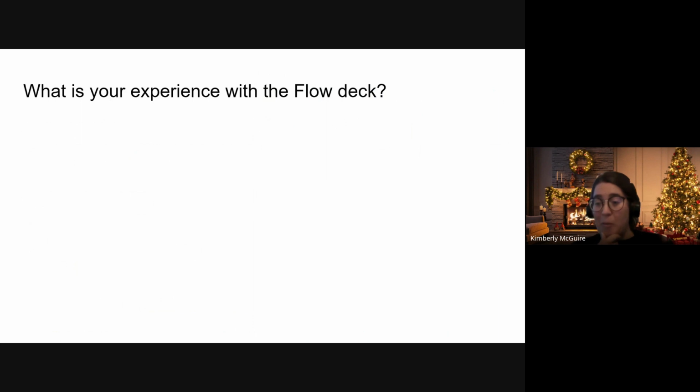So you just have to hope that at one point in the drift, it will fly over something that it can actually recognize as some kind of feature. What you can do, as the person that implements the behavior, is perhaps look at the variance of the EKF. If the position starts to diverge quite a bit, then perhaps you can give it a command to turn back to a location where you know it had better quality positioning. So yeah, there's a bit of luck involved. I hope that kind of answers your question.